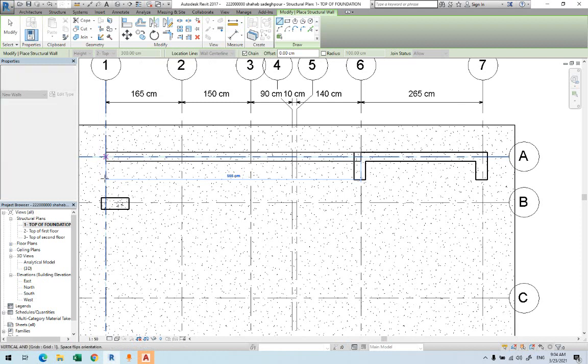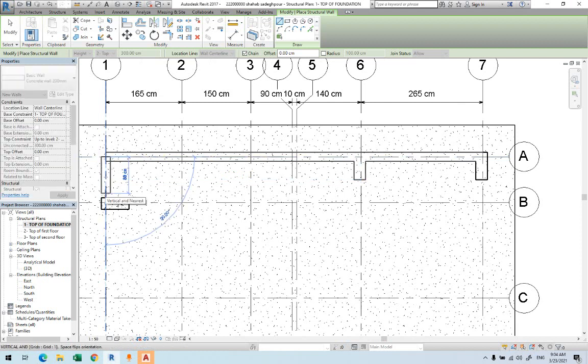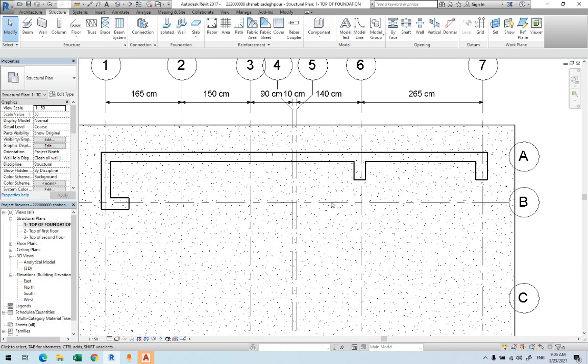For example, I'm going to come here, and then look, if I go like this, even the joint, it will try to connect them together. It will understand here, it will not be like the way that you saw it. So if I press escape, the columns, I had them there, so the wall is linked to the column. So I press escape several times.